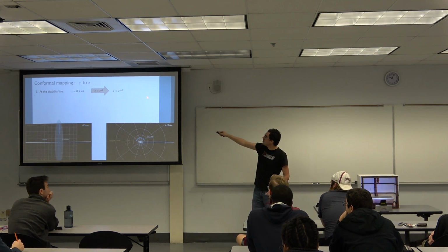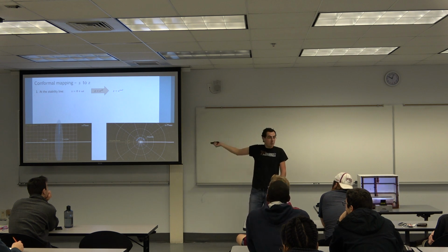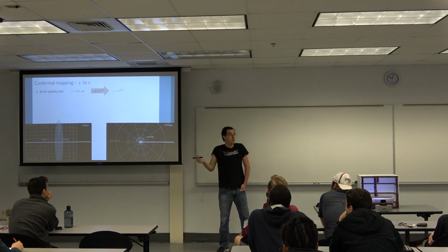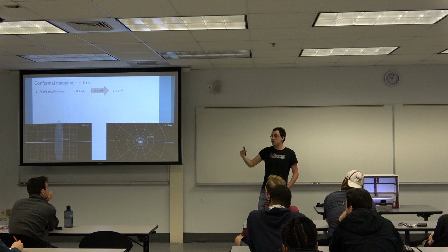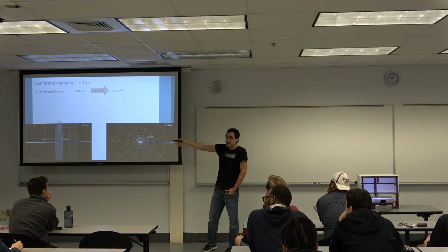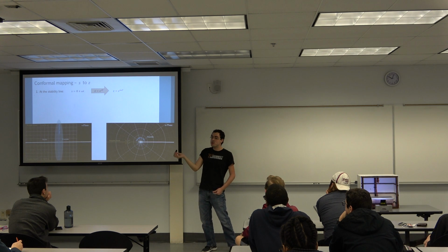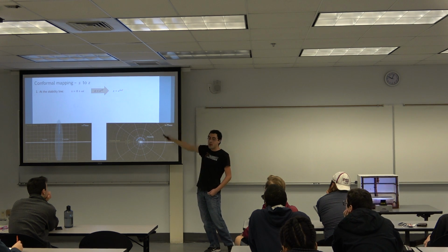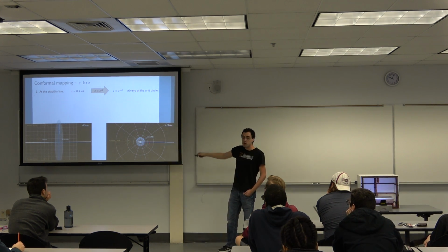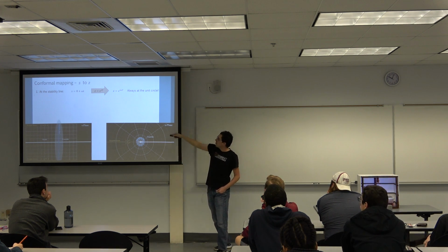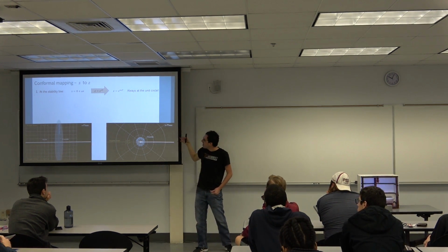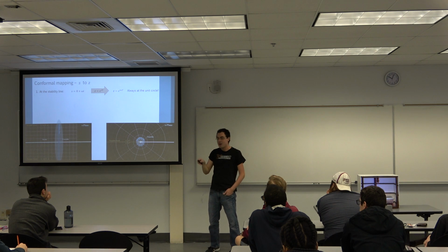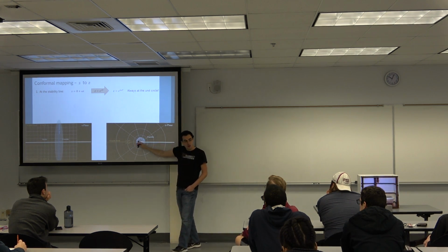So omega can be anything. T is our sampling time, or our sampling period. So this means that omega t is a number, any real number. So e to the j times some real number is just a phasor that goes around the circle. It lands somewhere on the circle given omega. So it's always on the unit circle. If you think about it, it might not be straightforward, and you kind of have to rehearse it a little bit. But e to the j something is always a phasor of unit length that goes around the circle.